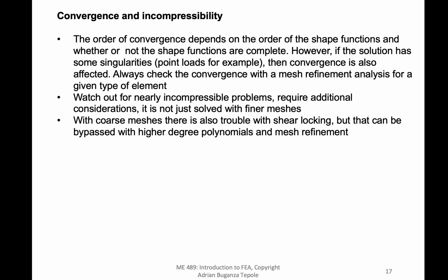So if you have a problem where you have point loads and you have this singular stress field, then even if you use cubic or quadratic elements, you won't get a higher degree of convergence. And so that's something that you have to keep in mind, that singular loading conditions will harm your convergence.